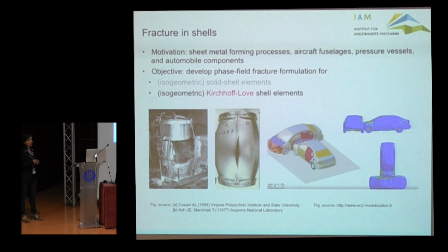So more challenging was going to Kirchhoff-Love shells, because in that case we only had a midplane. We only have a midplane, and we want to study fracture and account for the fact that the stress, of course, is not constant across the thickness. And this is, as I will show you in a second, quite a challenge if you want to have only one phase field on the midplane. You don't want a three-dimensional phase field.